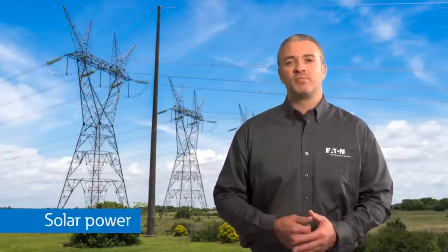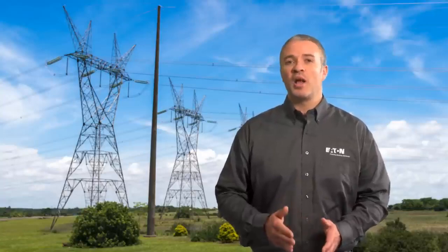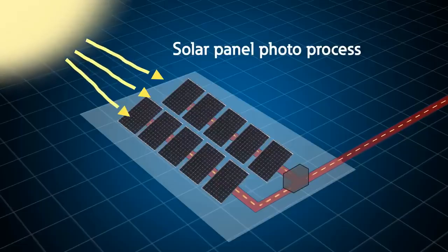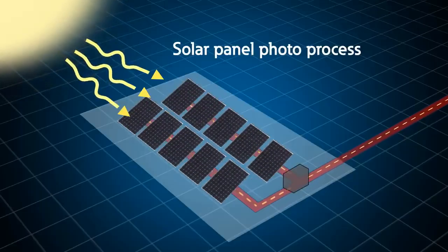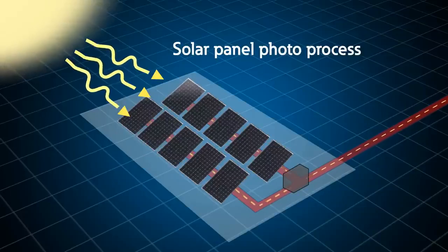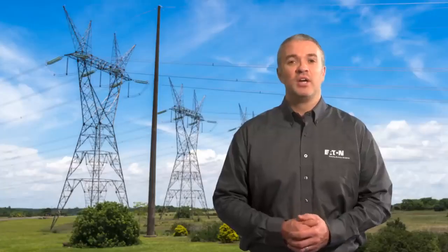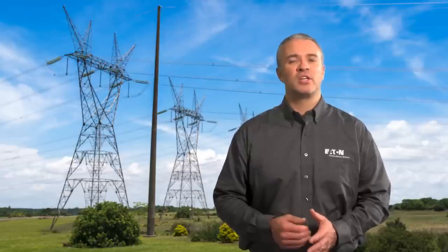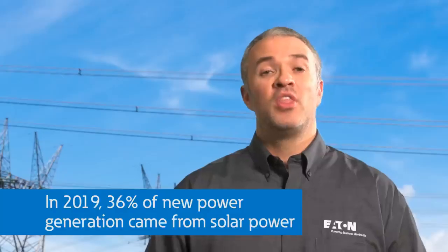Solar power has been on a steady rise as it becomes more available and a good economic investment. There are lots of incentives in place to promote the growth of solar generation for your home or business. Solar generation is a totally different type of generation compared to all the others mentioned so far. There is no prime mover or AC generator with solar panels. Solar panels strictly rely on the solar radiation from the sun to be absorbed by photovoltaic panels to produce DC power. The DC power is then converted into AC by the use of power electronics inside an inverter.